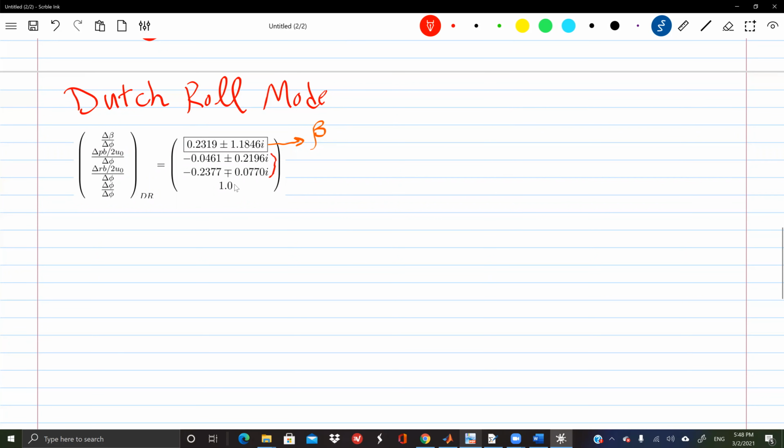Well, if we compare the roll and yaw rates, because this is the roll angle, I cannot compare the roll angle with these. To be fair, I would need to add the yaw angle and compare. So let's compare the rates, because the angles will go the same. They are of very similar magnitude: this is 0.22, this is 0.24. Unfortunately, I'll have to ignore one, seeing that this is slightly larger, the r. So indeed, this mode is associated with all of them: side slip, roll, and yaw.